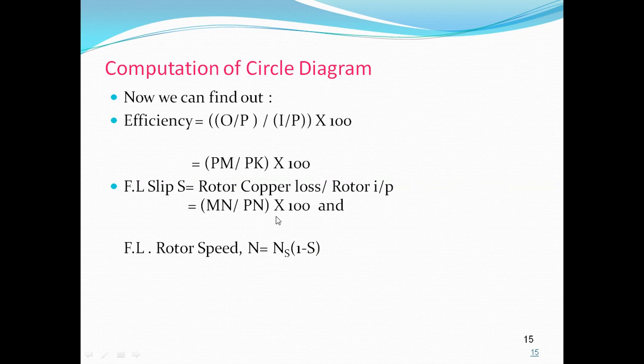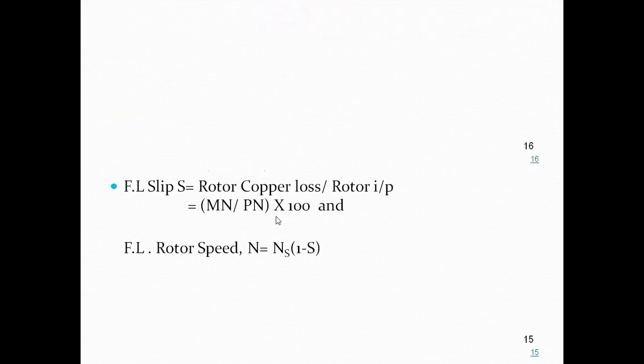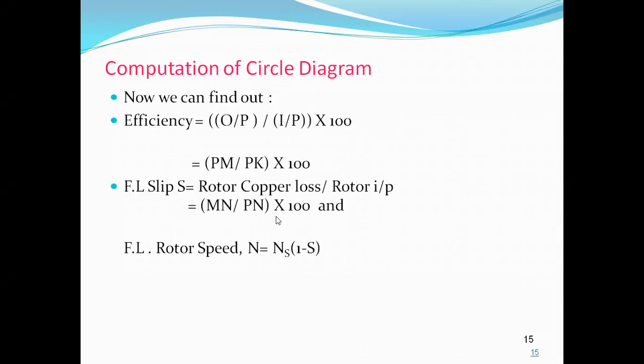Here we have the slip, and Ns we have to calculate, that is 120 f by P. Note down these formulas, these are important. After drawing the circle diagram, we can calculate the values by using these parameters.